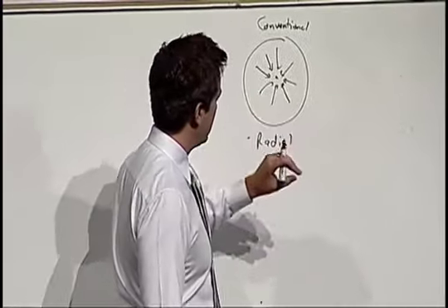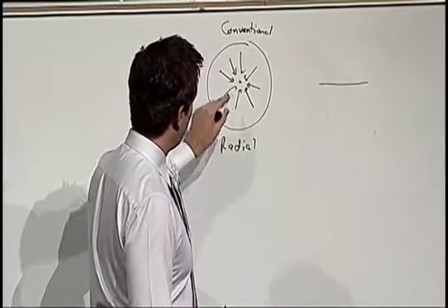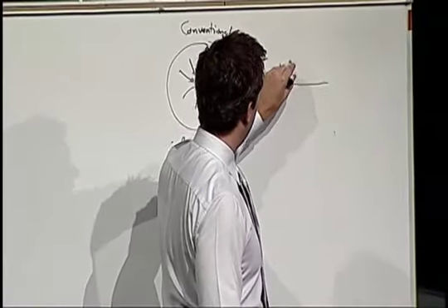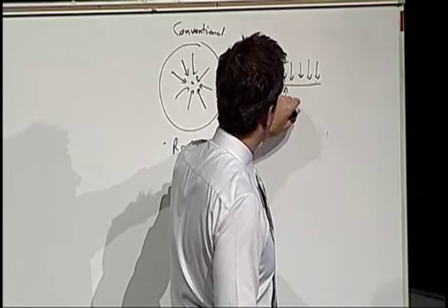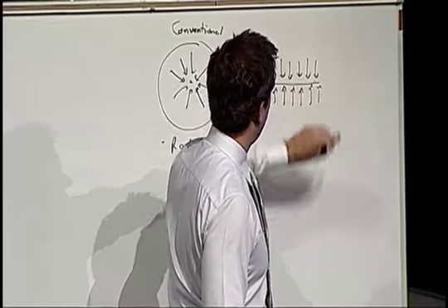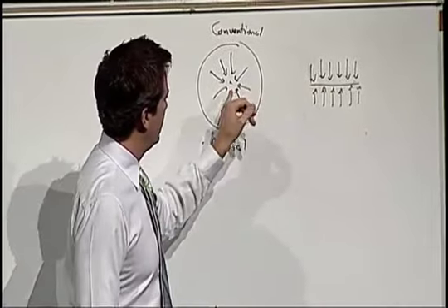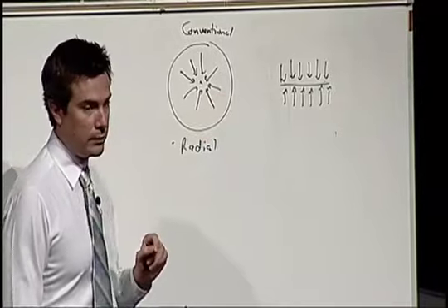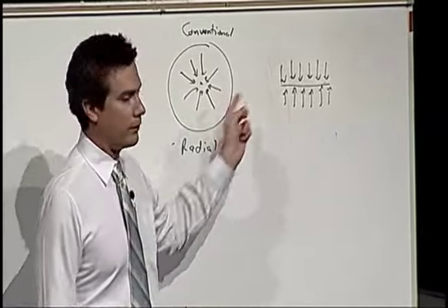So instead of having this situation, we have the situation where we've got a fracture. So we don't get the convergent sort of flow lines coming into the wellbore. Instead, what we get is linear flow. Okay, and linear flow is just like it sounds. All the flow lines are parallel. The production response from these two, luckily for us, if we're trying to tell the difference between them, are very different. We can immediately tell one from the other.